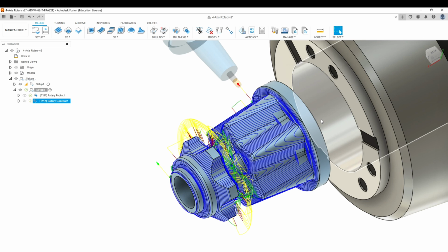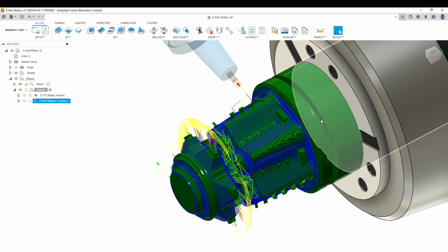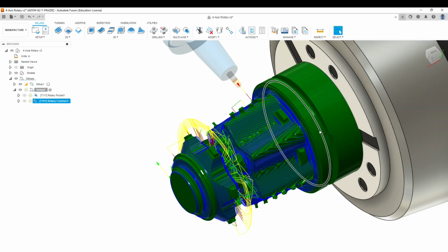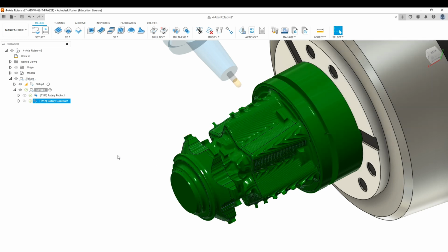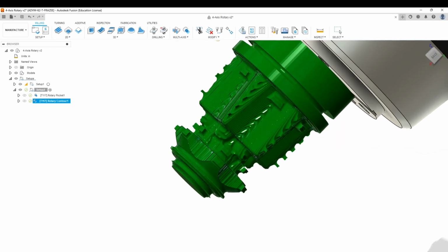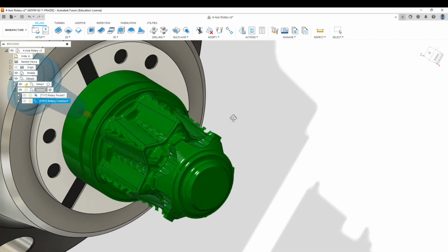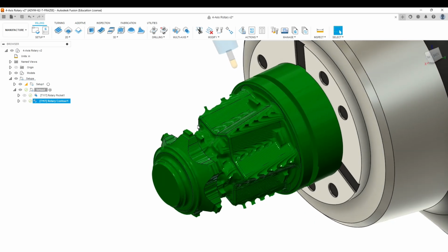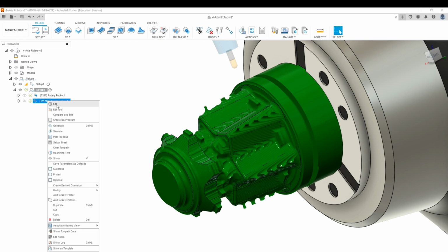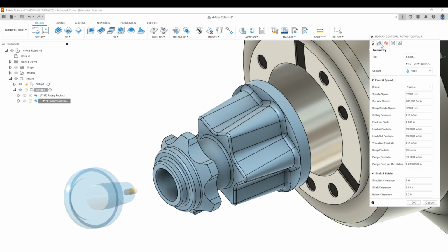Okay, so the rotary contour, it's giving us contour steps. They go in passes as it rotates, and it breaks that up into scallops. So if we take a look at this routine, this is what it looks like, minus the roughing that was done before this. So it really depends on the shape. You know, this might not be the results you're looking for. It looks like we left some islands here. Let's go back to our parameters and see what we can do different.